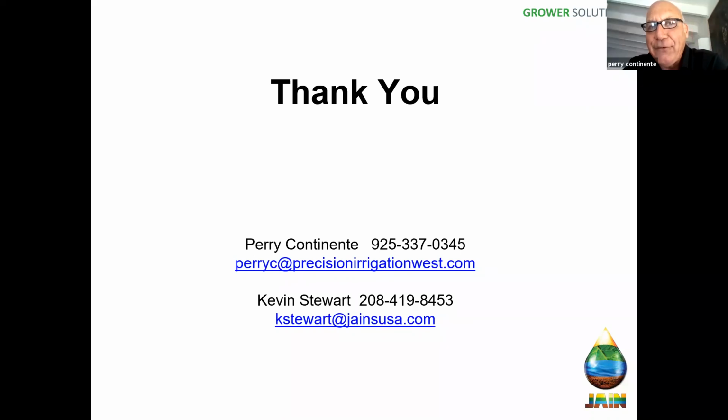Absolutely. If you go to the Cal Poly website, ITRC, they have a nice document that shows pictures of all the different things and what it looks like. But essentially, if you look at drip tape, the way that we determine what happened to it is you ask yourself, was that drip tape moving when that hole got there? If it was moving, there'd be drag lines. And when the drip tape is manufactured, it's manufactured in one direction, and when it's paid out in the field, it gets paid out in the opposite direction.